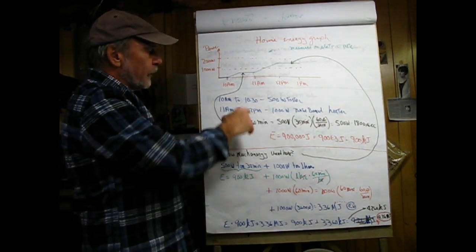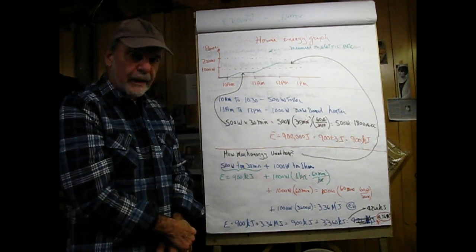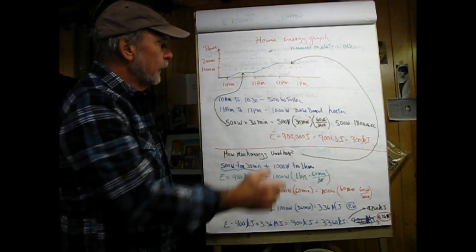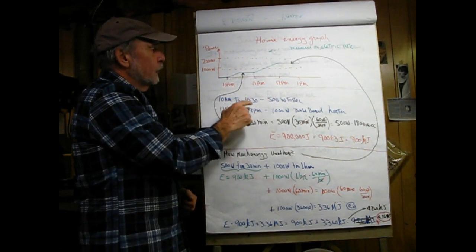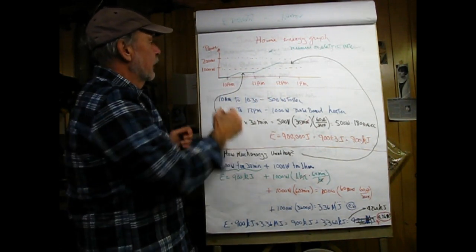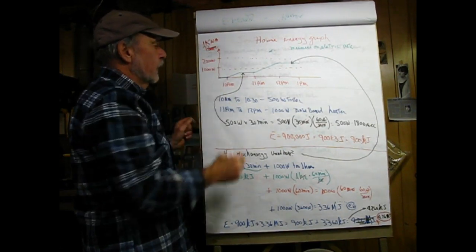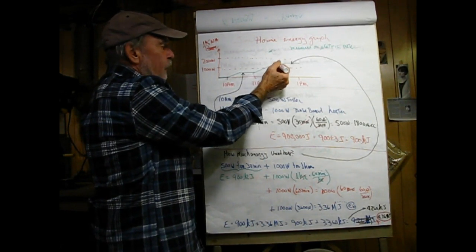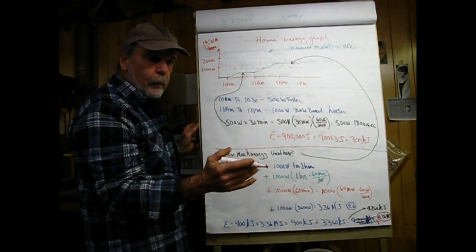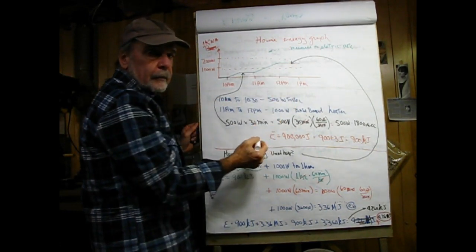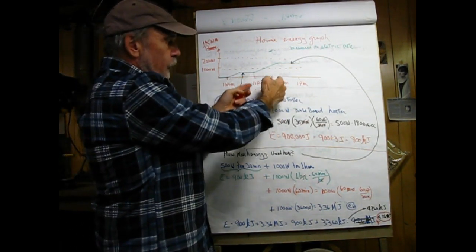Now let us suppose that I do nothing till 11 a.m. and then say I turn on a 1,000 watt baseboard heater to heat up a bedroom or something. Again, this will ramp up. This is going to be on for 1 hour. Now the total power, and actually this should be in kilowatt hours, it's an energy, will now sit at 1.5 kilowatt hours. And since the baseboard heater went off at that point, again, this remains flat. So the electric company wants to be paid for this usage and this usage.